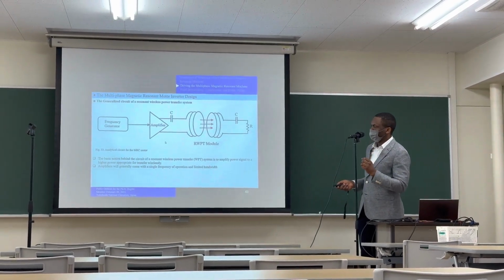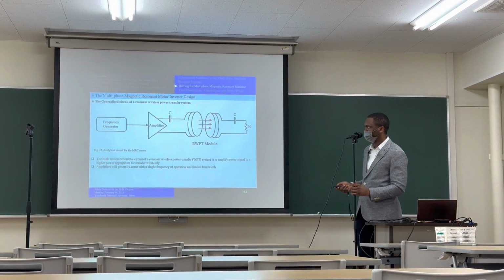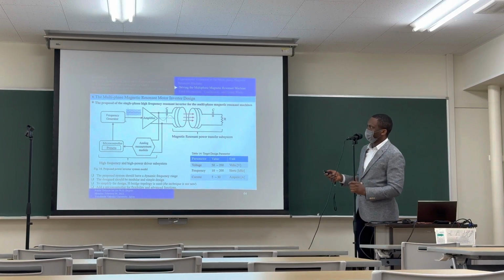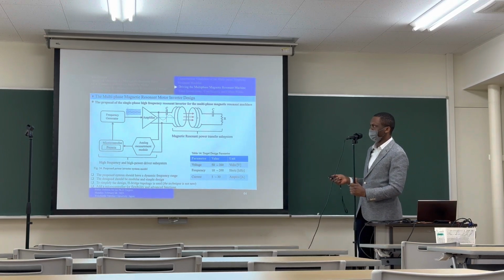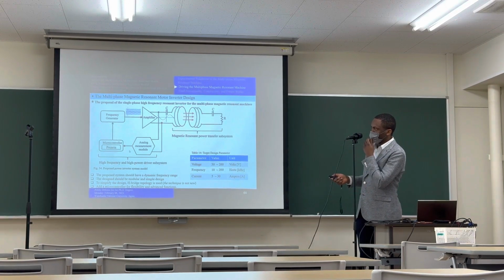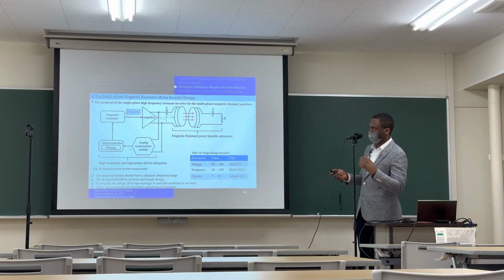So this is the idea, and it means that we have to design an electronic system that is based on this, because this is how the motor works. The main idea is we are going to use a frequency generator that generates a low-voltage frequency, and then we use an amplifier. Then we amplify the frequency, make it resonant, and pass it through one of the phase coils, and then it meets the other phase coil at the motor side, and you can create rotation. And we're going to add some sort of microcontroller that will control this frequency, and you can still add something to measure current here.